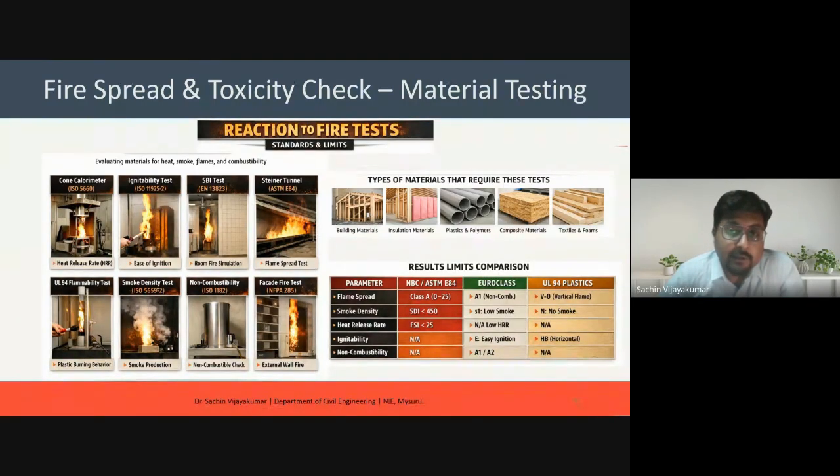Otherwise, what will happen? The Kamla Mills fire that I showed you, which caught fire on the facades and started to spread to the vertical elements, the same thing is going to happen. So before adding any new material, we may have to test those materials for reaction to fire. And there is greater potential. If you are able to come up with these HRR indices and their relationship with all these elements, bingo, you can do CFAST modeling or maybe FDS modeling. You can determine the active fire safety requirement based on your reaction to fire tests. These are some of the futuristic opportunities that you have.